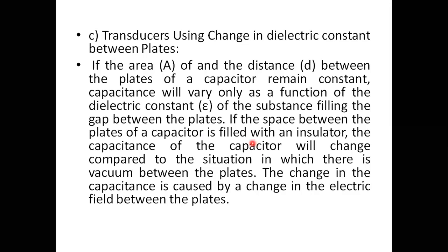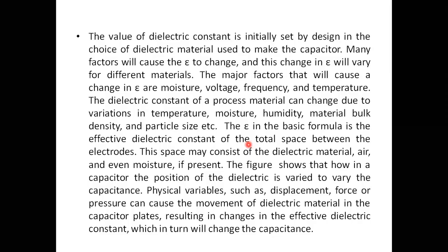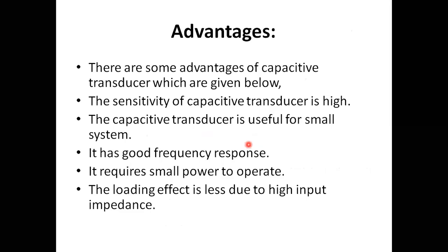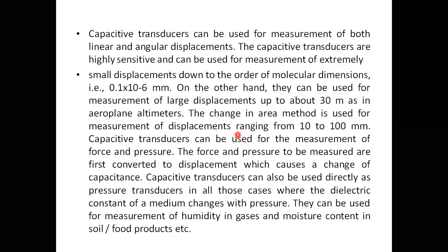And if I use change in dielectric constant, then I can measure small displacements also. Changing dielectric material gives me measurement down to 0.1 into 10 power minus 6 mm also. So I can measure very, very small measurements. Where can I use this capacitive transducer?